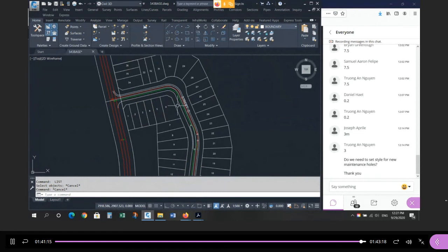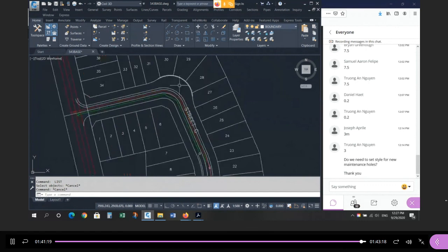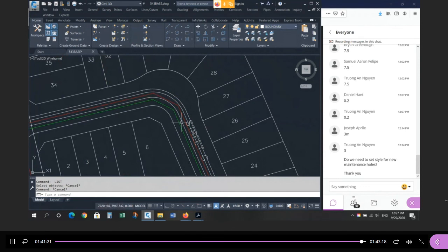You have to navigate bends with maintenance holes. So every time you change direction in plan, you need a maintenance hole. And when it comes to the cul-de-sac in here, or sorry, the crescent in here, you have to have this short turn in anticipation of the servicing on the outside of the curve. So that's how you lay out your storm and sanitary maintenance holes, right? Maintenance holes and pipes. Okay. The size, the slope, we'll worry about that later. I just want to see in the map where you're going to put these items.